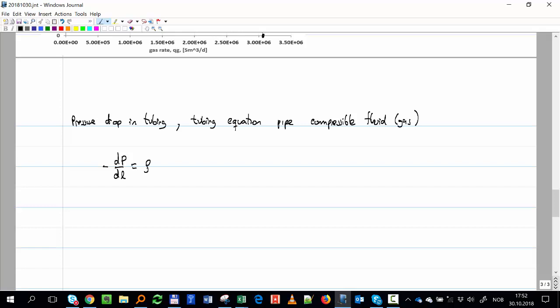One of them is first the hydrostatic difference, right? Which is density, gravity, and yes, here we have the angle, the inclination angle. But I'm going to define my angle. If I have my pipe like that, I'm going to define my angle here, this alpha, from the vertical, like drillers. I'm not going to define it from the horizontal. That's when we use it for transport. But for the tubing, I use it from the vertical. So here I have the cosine of alpha.